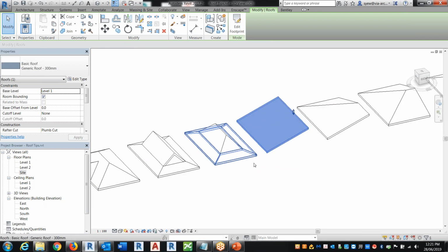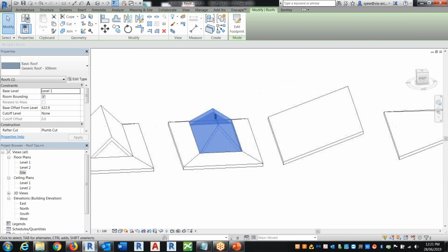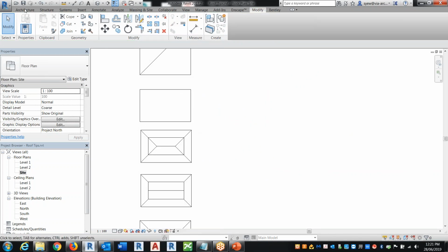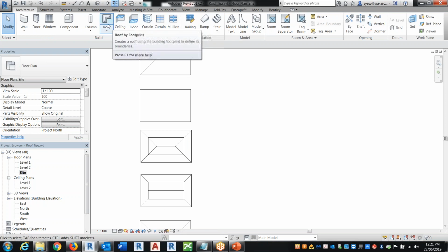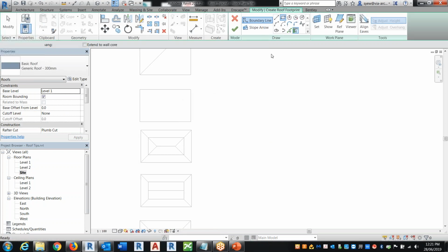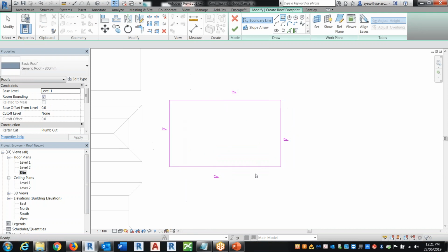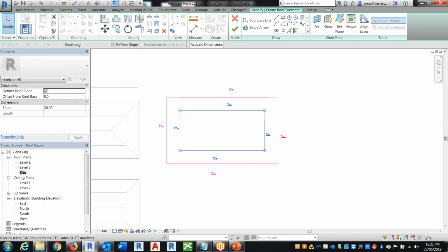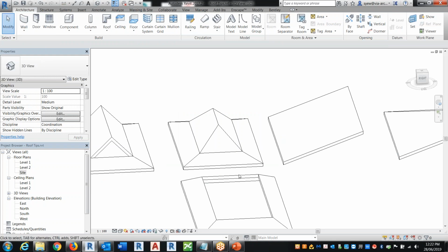All right, how do you create this? Now, this one is kind of easy. All you have is two roofs. The first thing you would do is create a roof. If you want an opening, just go offset. Let's assume this is 900, for example. That's too little. Let's say 2 meters. Then make sure there is no roof there, and once you do that, it becomes a hole.